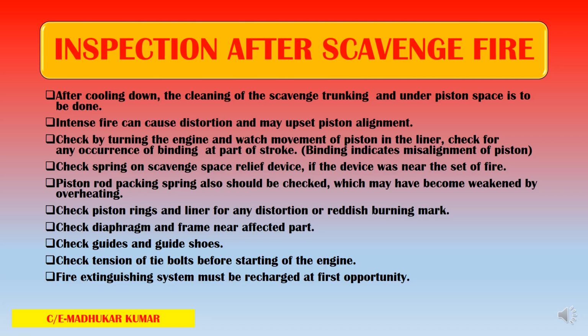Now, inspection after the scavenge fire. Actually, all these questions are asked in the orals. What inspection will you do after the scavenge fire? So these are the points. After cooling down, the cleaning of the scavenge trunking under piston space is to be done.